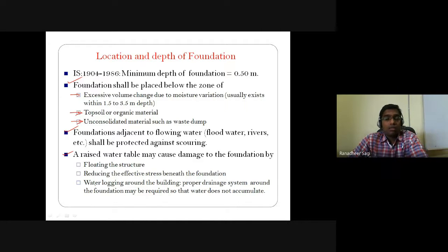And you should avoid the waterlogging effect happening around the foundation being constructed. It means that water should not get stagnated around the construction region of your foundation. If water gets stagnated around the site or the surroundings of the foundation, there are all possibilities that the foundation might get damaged, or the strength of that foundation can decrease over time because of the erosion effect in the steel bars placed inside the construction of that particular foundation and so on.